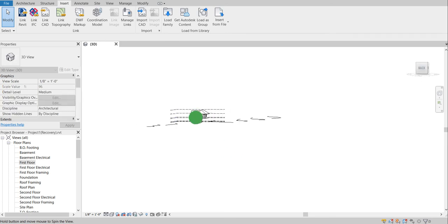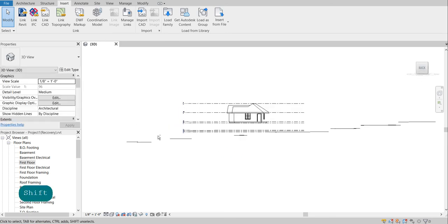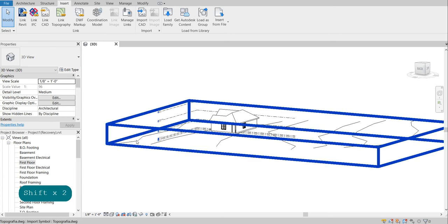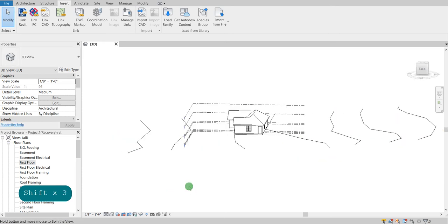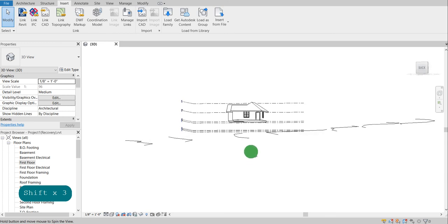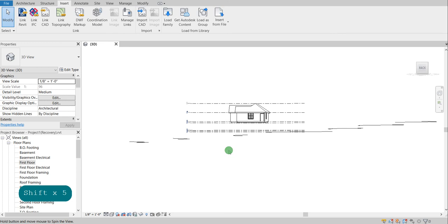So I have here my contour lines, and then you see that I just have one layer here. Okay, so I had to create just a CAD file with just that layer, or I have to make sure all contour lines are on the same layer. Okay, and then you're gonna see why. And they also have to be on this axis. You see here how they're moving up. So in CAD, they need to be on that level as well.